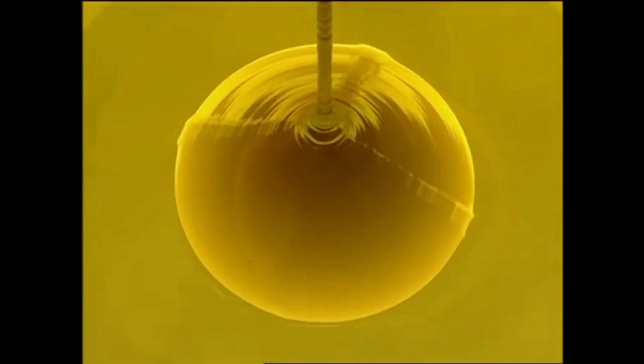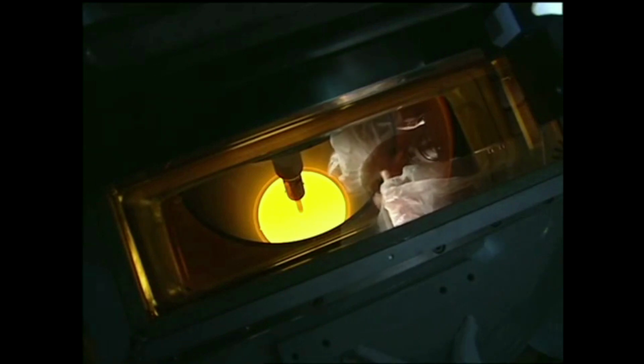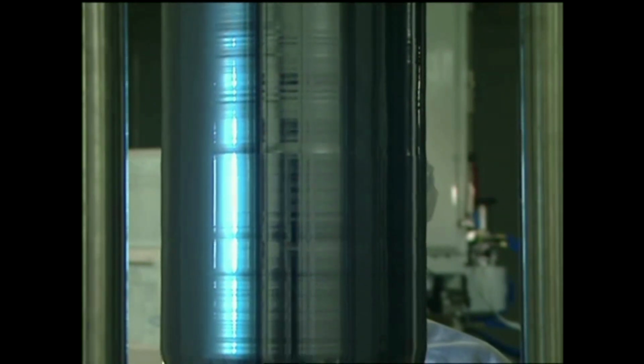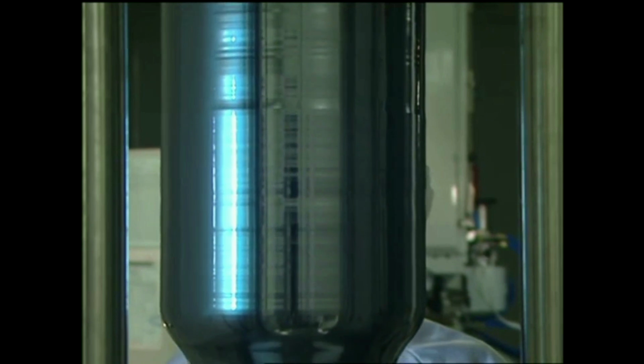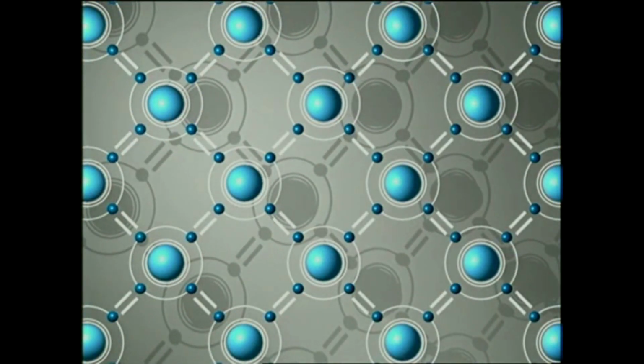This is the raw material. Chips are made of sand. It is made up of silicon dioxide. Silicon is the second most common element in the earth's crust and only exists in bonded form. Complicated chemical and physical processes are needed to convert silicon into a crystalline form and make sure the crystal will meet all the requirements necessary for chip production. The final product is a monocrystalline silicon rod of highest purity. This means the rod has only one impurity atom for every 10 million silicon atoms.